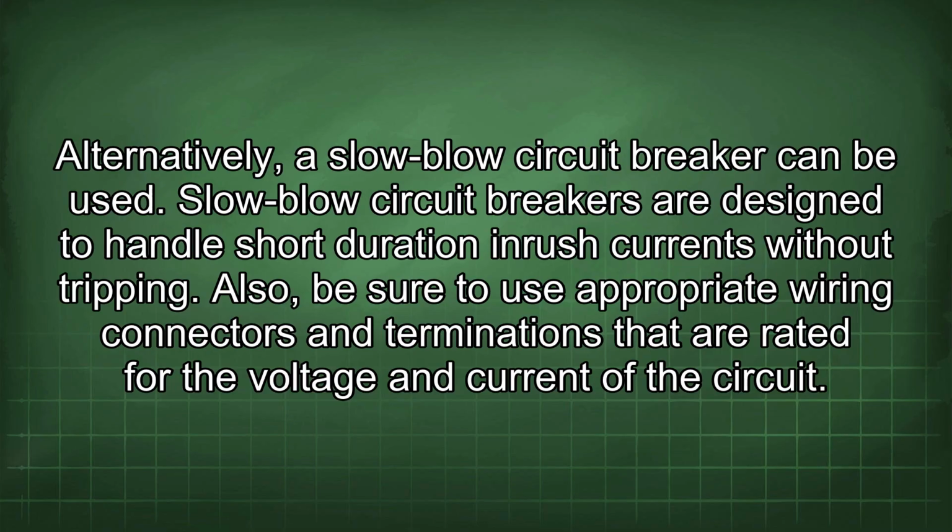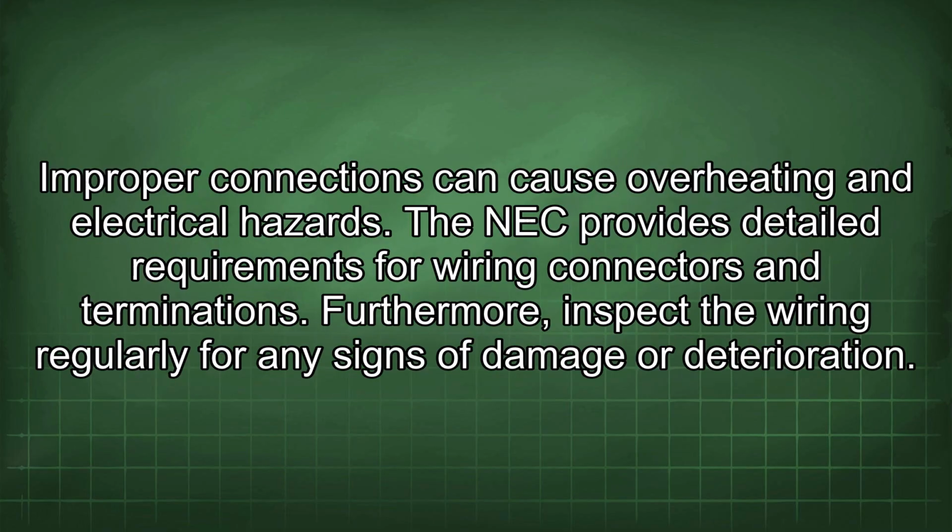Alternatively, a slow-blow circuit breaker can be used. Slow-blow circuit breakers are designed to handle short-duration inrush currents without tripping. Also, be sure to use appropriate wiring connectors and terminations that are rated for the voltage and current of the circuit. Improper connections can cause overheating and electrical hazards. The NEC provides detailed requirements for wiring connectors and terminations.